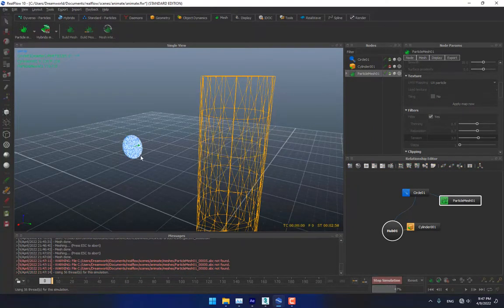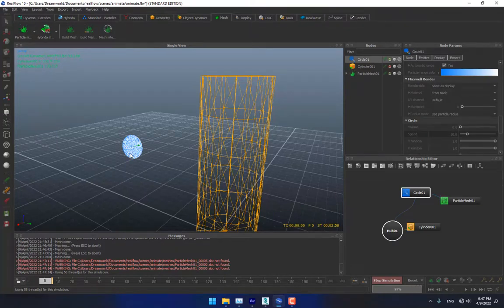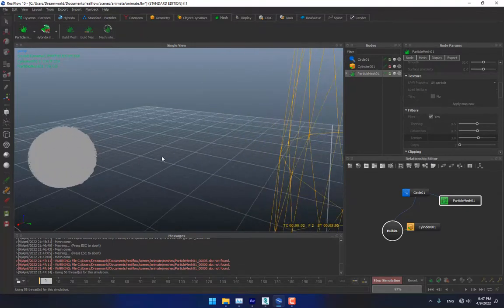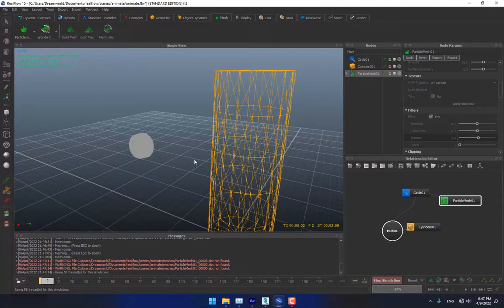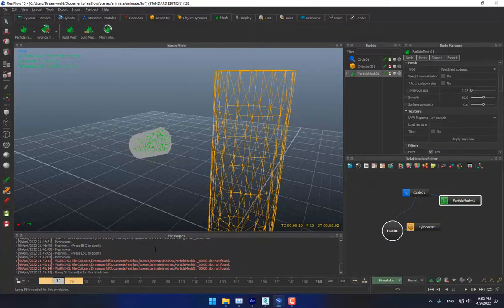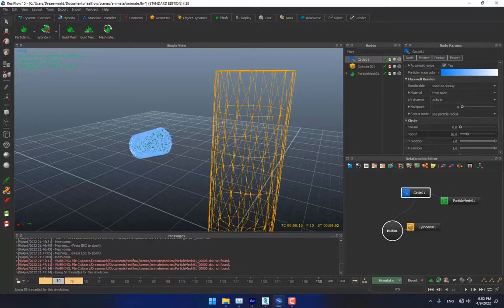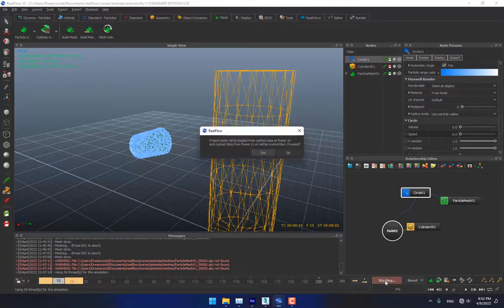This is the final setting of creating liquid, because there is the mesh you can see when you zoom, and this is the circle particles, and wait up to 60 frames. So after 10 frames, go to speed, circle speed, change to 0 and continue your simulation after frame 11.